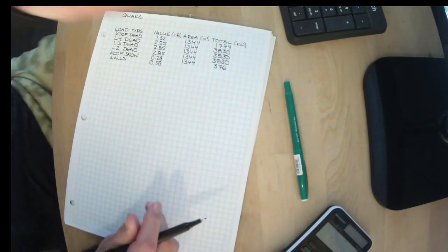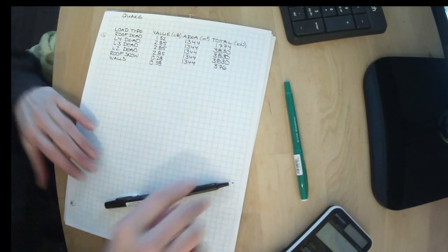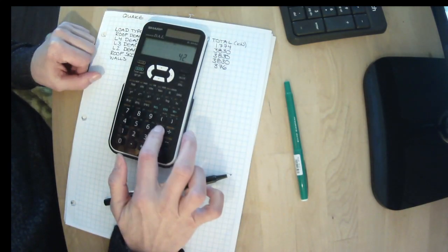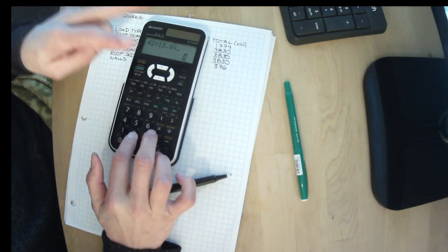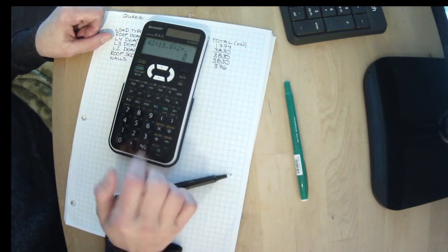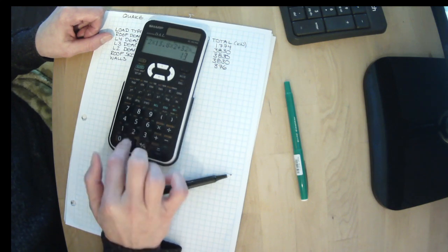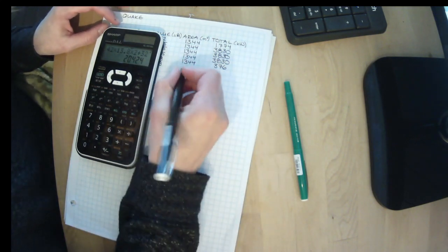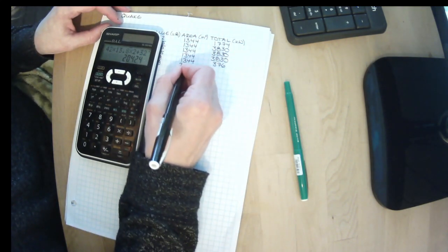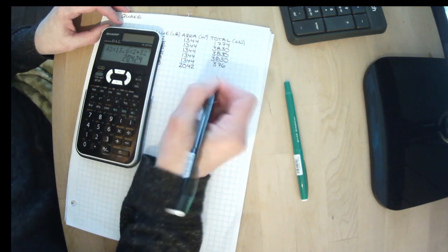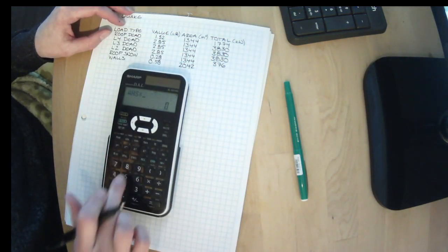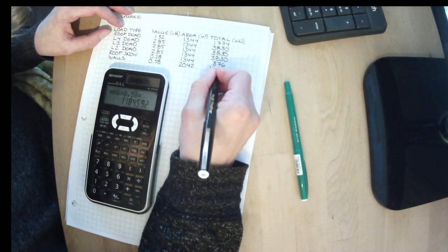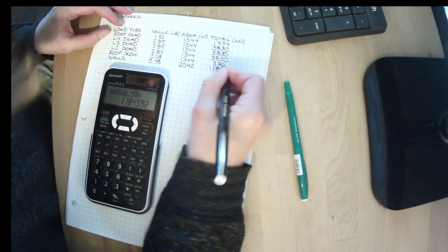The total area is all of the walls around our building, or 42 meters times 13.8, and we have 2 of those sides, plus 32 meters times 13.8, and we have 2 of those sides. So a total surface area of 2,042 square meters. Times that by our 0.58 kPa, we have 1,185 kilonewtons.